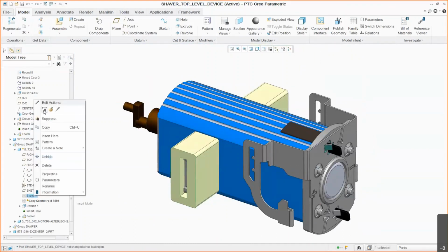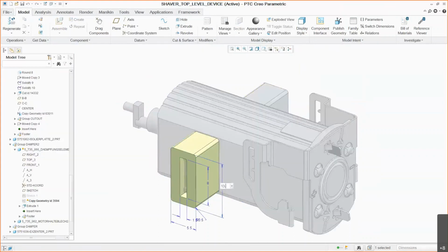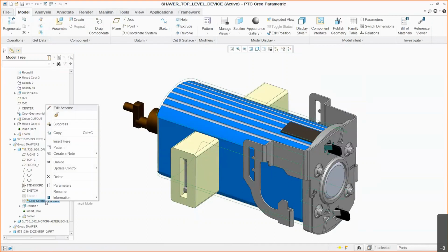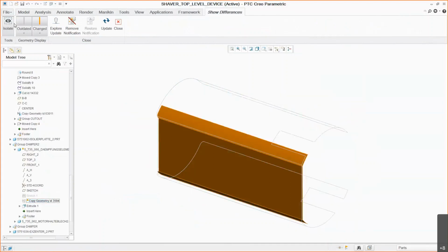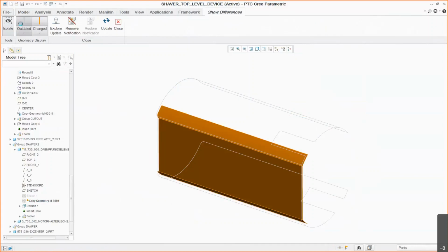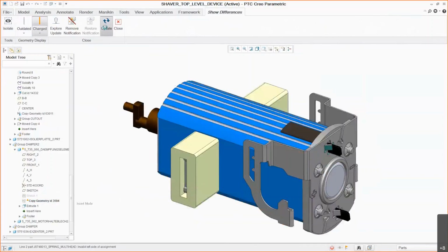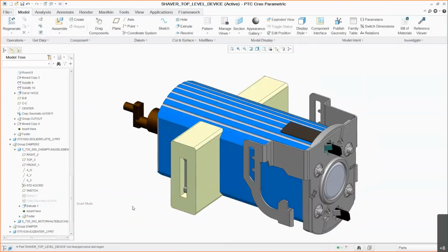So this is one of the great things about having your files opened in Creo: no load times, no geometry errors, and you get these automatic updates. So you don't have to manually make these changes when they give you the new motor. Here we have the bumpers. If the surface has changed a little bit, not a problem, no problem with the different dimensions. All I have to do is hit update and that geometry will correct for you.